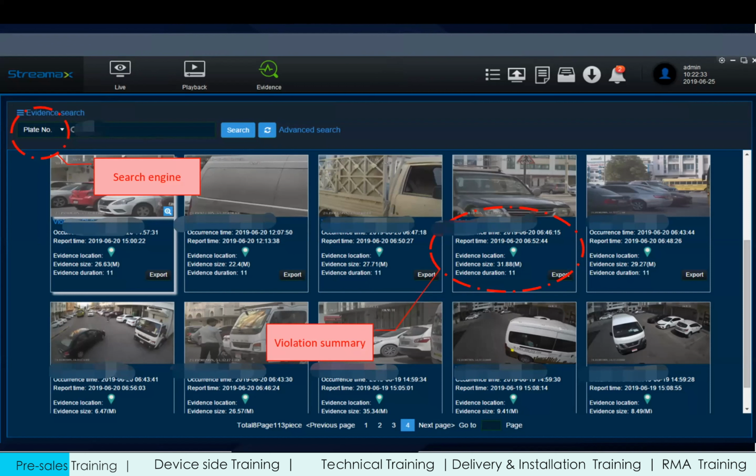The second level, it will send the alarm live to the platform, so the control room person can talk with the driver to ask him to have a rest. And the third level, the device will mark the alarm and upload maybe only 5 seconds of this fatigue alarm to the platform. This serves as evidence to evaluate the driver later.